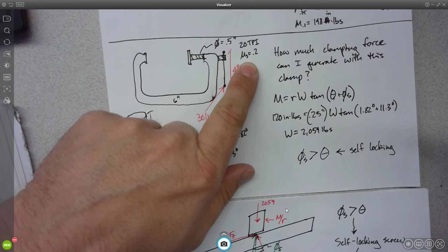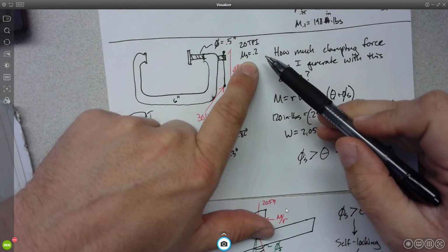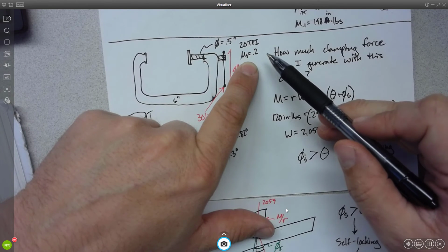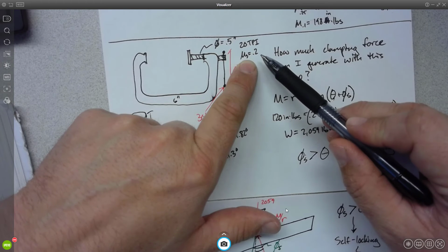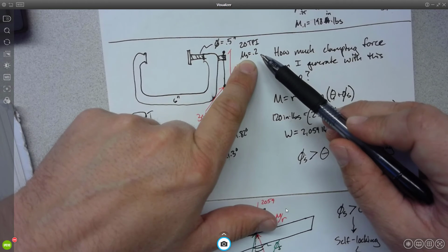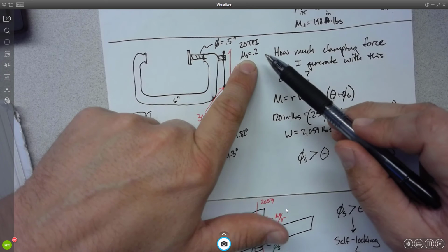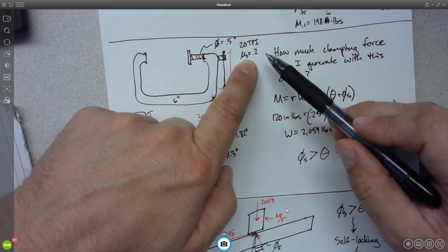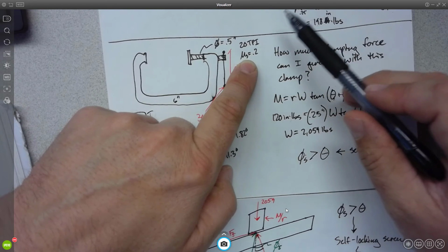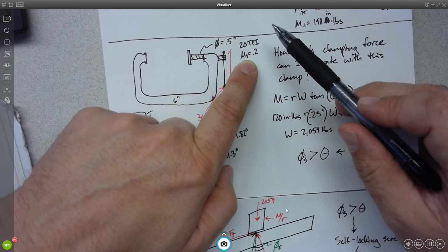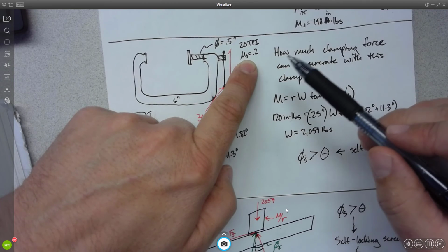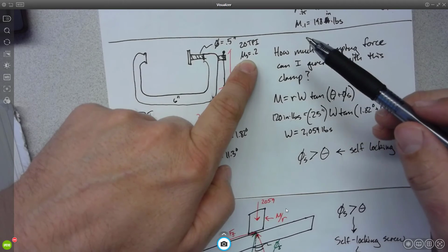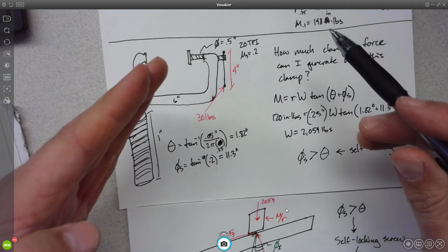Although you could potentially make a really cool screw that doesn't have a constant mu static, right? Why would you do that? Because maybe you want to lift a really heavy load as easily as possible, but you don't want it to unscrew itself. If you made it so that it had a really small coefficient of static friction as you thread in, versus a really high coefficient of static friction as you thread out, you could make it self-locking. Or even if you just had ridges on it.